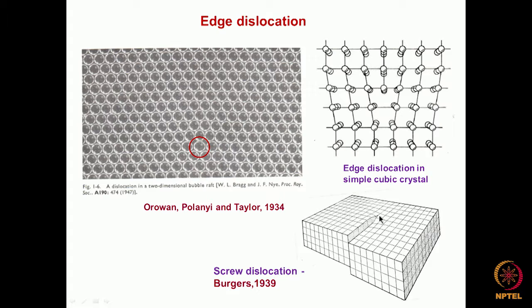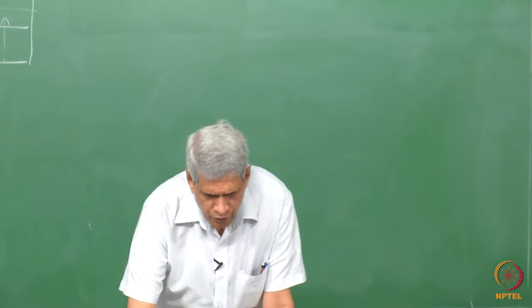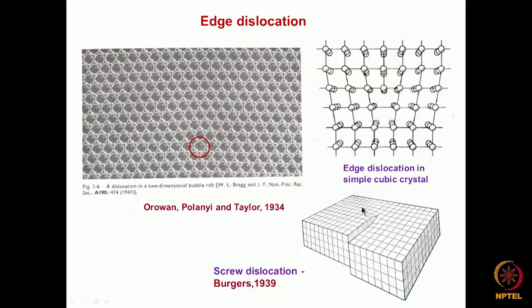This is something like if you take a screw, I try to rotate one rotation, I move one pitch forward. If I go again, I will go forward. Like that it happens. So from here to here, if I try to move from here, rotate it like this and try to reach here, I come down. One pitch has happened. So that's why this is called a screw dislocation. Yeah, that step will come. So this is called a screw dislocation.